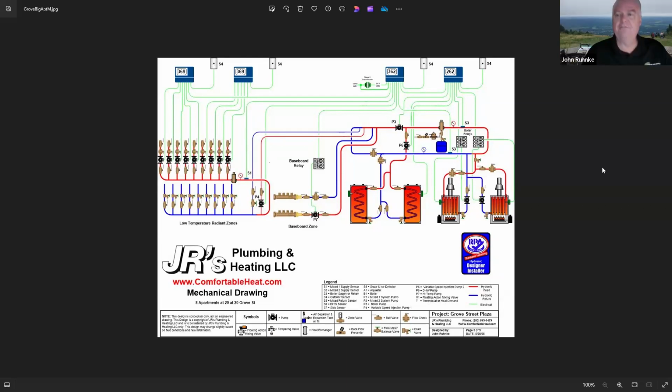Go ahead. Right. The speed at which the air is moving through the combustion chamber plays a big role in how the heat is being transferred. So that velocity needs to be part of the equation. The analyzers currently are not using velocity in the equation, and that's why they give a false reading. So that's something maybe academics could work on. Maybe they could figure out a way of including velocity in the calculation, right? Sure.